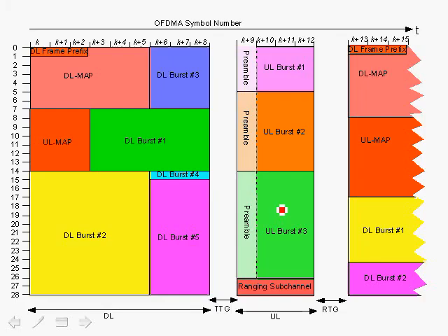Let's go back to here. So basically, the downlink frame prefix designates the rate that is going to be used for the downlink. It also specifies the total number of OFDM symbols that are going to be used, 10 bits, and also the number of subchannels. In this case, we're using 28, and of course, it could go all the way to 32.